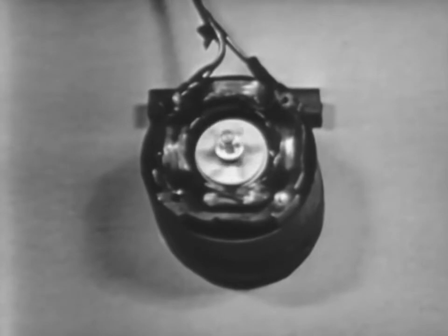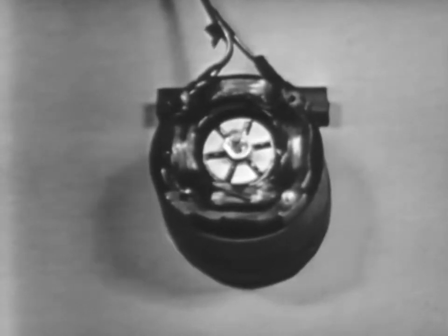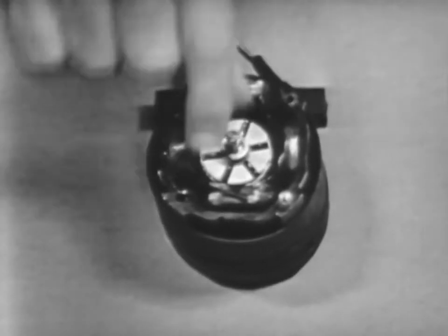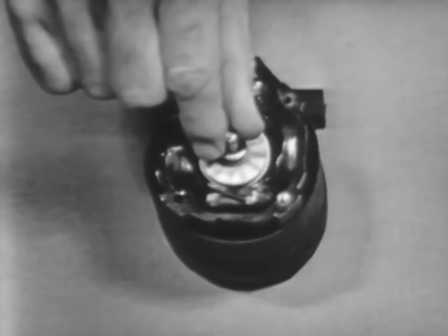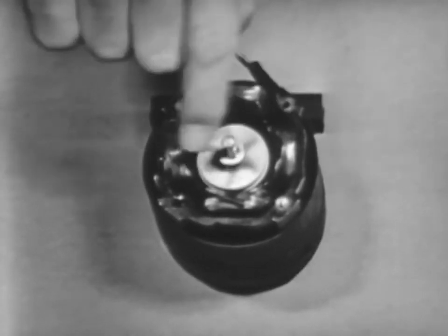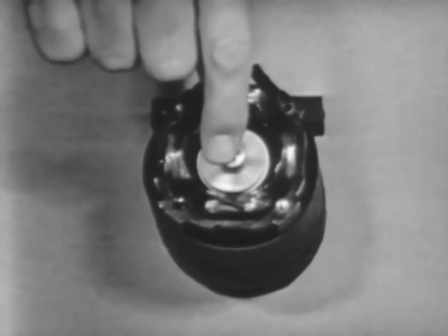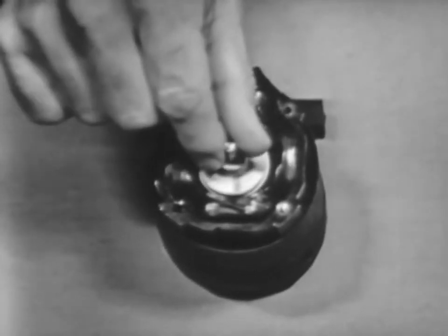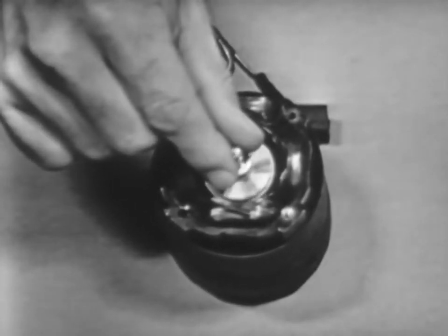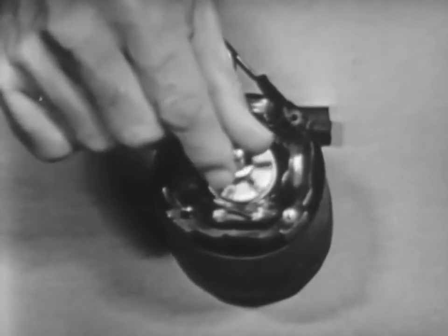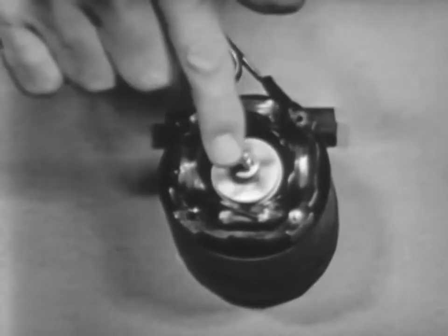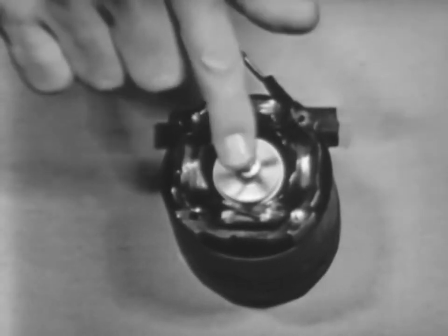Which brings us to item 5, which I believe you can have. Exactly. All right, the rotor of the induction motor does not rotate as fast as the magnetic field because of several forces that act on the rotor. One, the internal load, that is rotor weight, the little fan, the bearing friction, and so on. And the external load on the motor, such as the gears, pulleys, or the fan blade, or in this case, my finger. As I squeeze it a little bit, you can see that it turns slower. Right. So the rotor has got to go slower than the rotating magnetic field in order to have relative motion so that it can become an electromagnet.